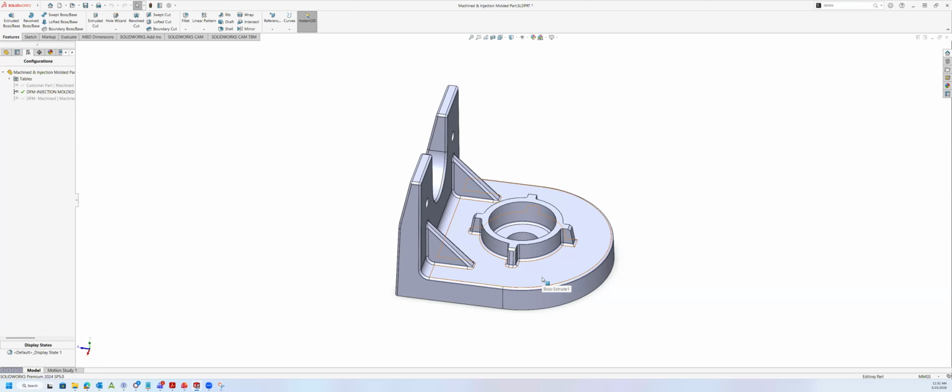When you're injection molding a part, you want to ensure uniform thickness to ensure smooth and consistent flow throughout the part, and help prevent any warpage due to unnecessary cooling and hot spots throughout the part itself, or faster cooling and hot spots. So when you don't have a uniform thickness, it will result in a lot of defects such as warpage, sink marks, and much more.